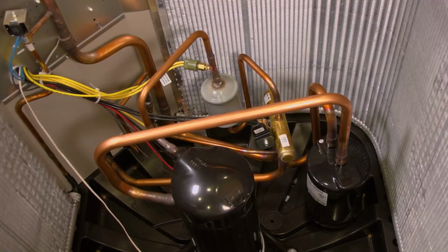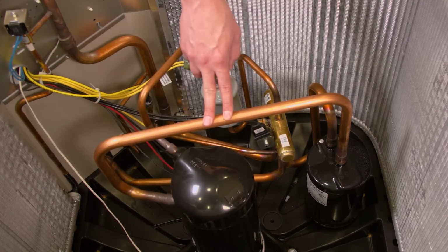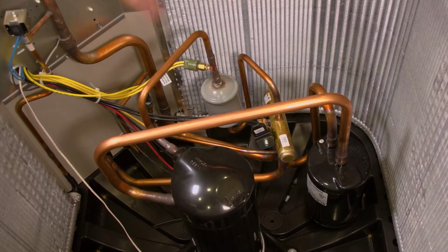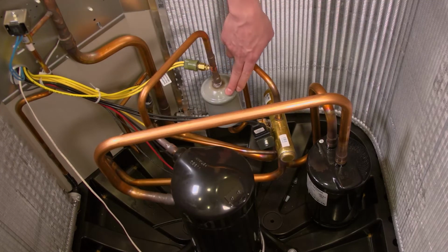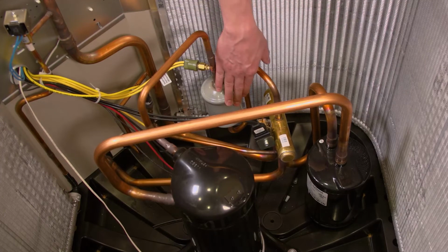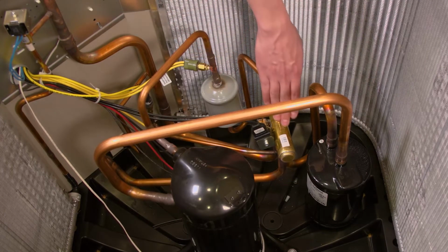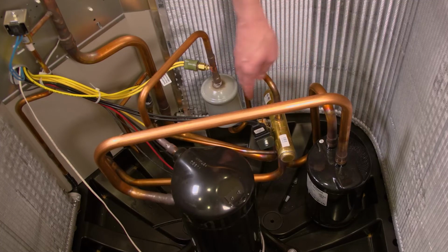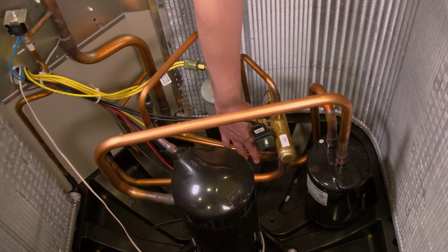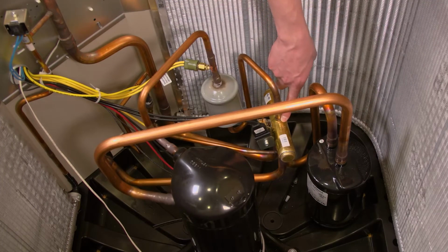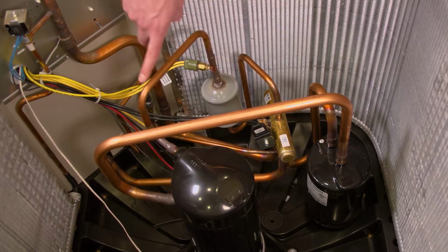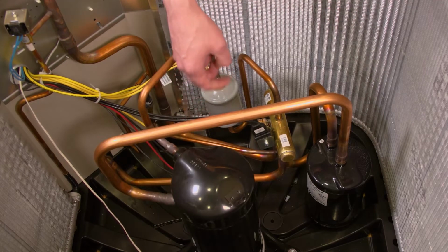The first thing I want to point out to you guys is, one, this line here is going to be our common suction line. It goes back to our compressor. Second thing is this is your discharge line here, and this part is a muffler, which often gets confused as a filter dryer, but this is just a muffler. And when it comes to your reversing valve, you'll have 3 lines that come off the bottom of the valve, and then you'll have your discharge line that comes on the top. Now again, this line runs through your muffler and back to your compressor.